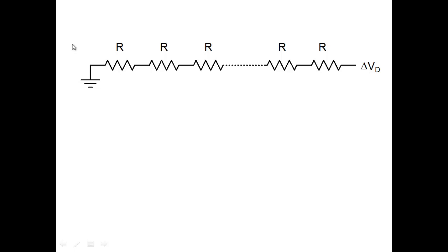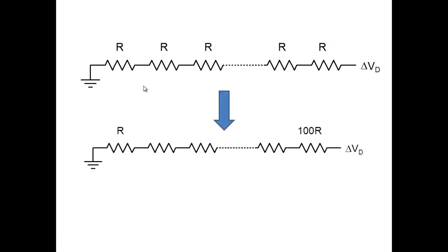So the voltage, let's focus here. The voltage increment would be how much? 20 millivolt. 20 millivolt divided by R would be the increase in the current. So my drain current would increase by 20 millivolt divided by R. Right? Okay. Now let's go to the other extreme. The other extreme is I've gone towards the pinch-off region.